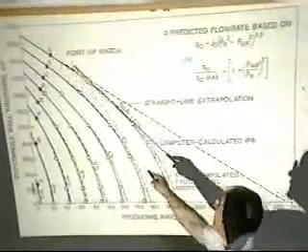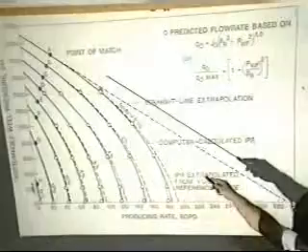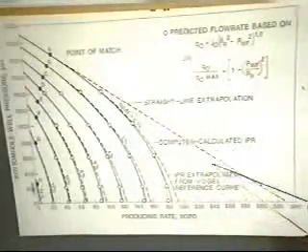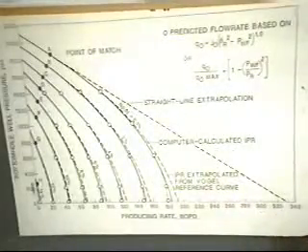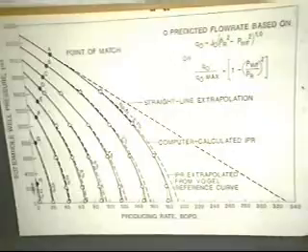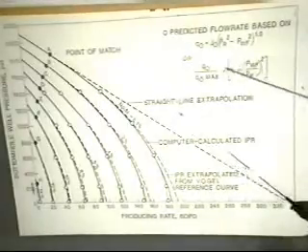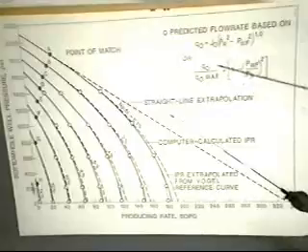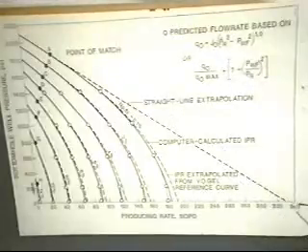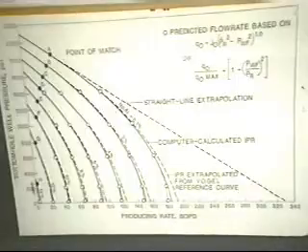If you draw a line through match point A and continue as a straight line, this would be the productivity index expressed in terms of a difference in pressure, delta P. And you'd indicate that that well flowing at that rate, at whatever flowing pressure that is, has an absolute open flow potential of about 330 barrels of oil per day.